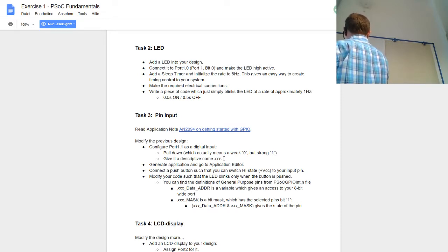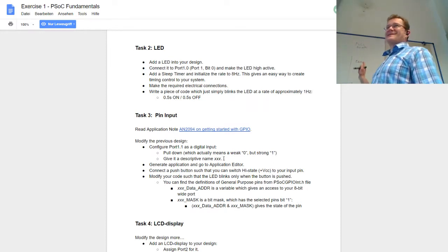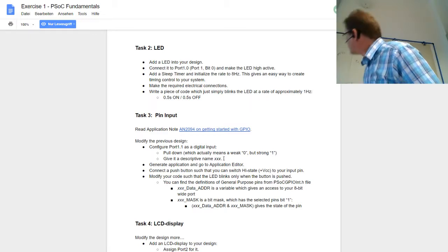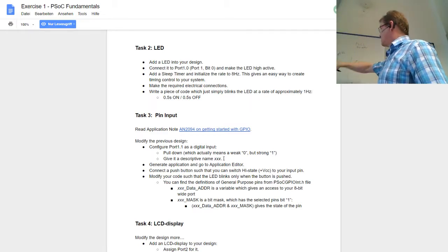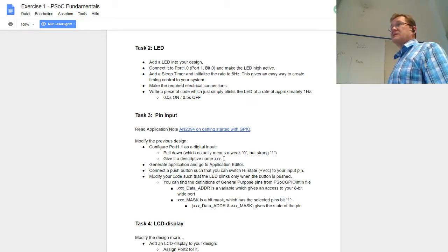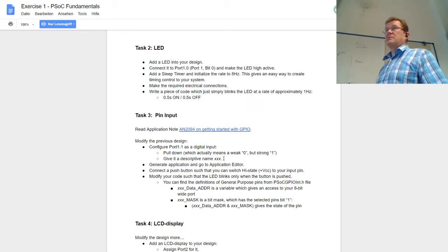This is the processor inside, and there's a pull down resistor inside, which is a good idea, since then you can have just a switch to plus VCC. So that's a button switch. That kind of switch we have on board. SW is this kind of switch. Pressing the switch gives state 1, but this pull down resistor gives the initial state 0.